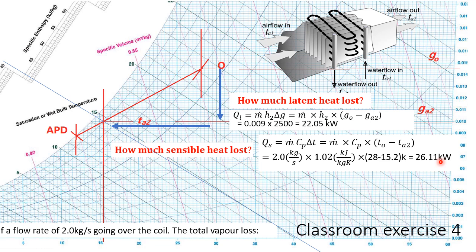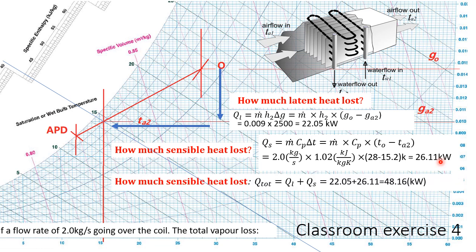Okay, so we use these two formulae to calculate latent heat and sensible heat. We put them together. So how much energy is lost from outdoor air to off coil? Previously, before going in, it has so much energy and lost so much, right?